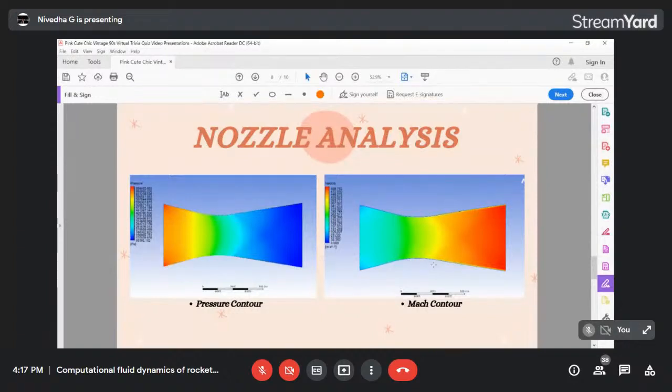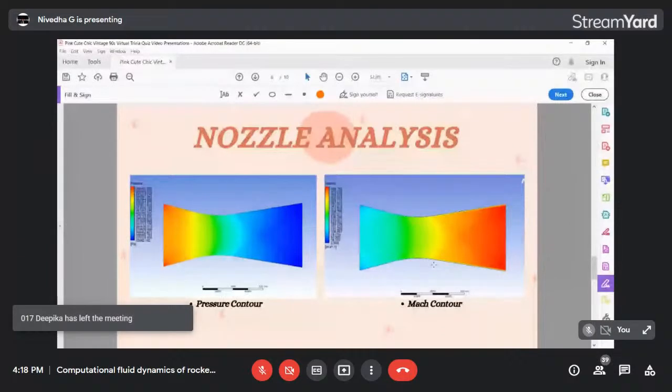It is also suitable for viscosity elements. Here it is air. If you use any other propellants, you'll have viscosity, and it is also suitable for that. For aerospace applications, we use Sutherland viscosity. And my operating pressure is 0, but my inlet pressure will be 5 bar at this point of my nozzle.